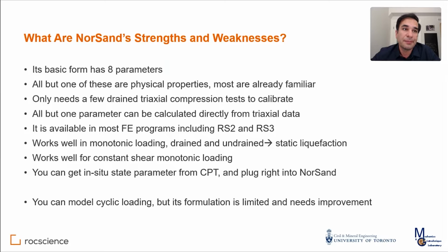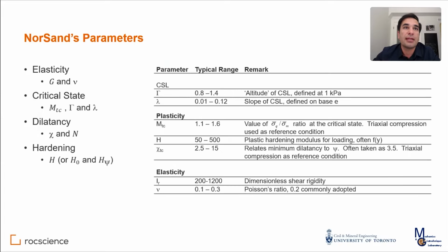Norsand is not meant to do cyclic. Mike Jeffries has done cyclic with it. It does have the parameters, but it wasn't born that way. So cyclic loading is something that it sometimes struggles with, needs a bit of expert input and calibration to do well.